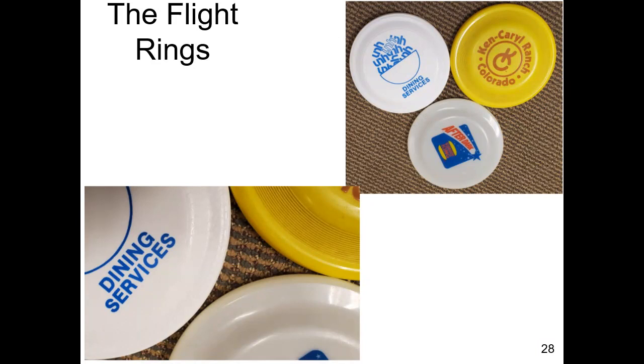Some of them will just have a smooth surface, a Brand X, and then there's Humphrey Flyers, and others will have some other type of roughness element. Why? They're trying to trip the boundary layer. Why? When you trip the boundary layer and you have a turbulent boundary layer, you have less wake, less drag, so the Frisbee not only flies farther, but it's more stable.